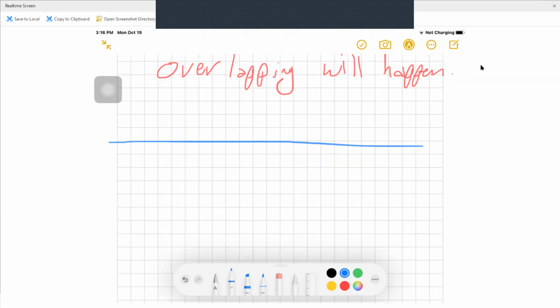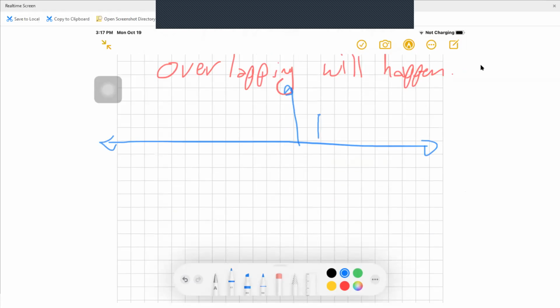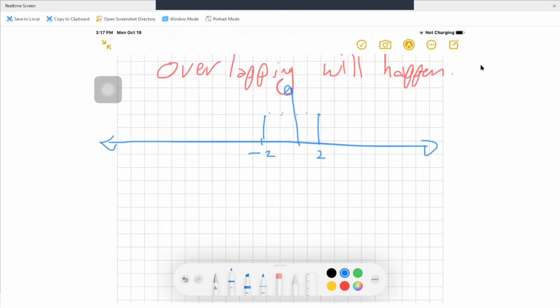Okay, starting with the spectrum of the signal. Of course, going back to the same story. Well, here we have two frequency components, 2000. Of course, the 2000 frequency magnitude will be 2.5, for 2 kilo and minus 2 kilo. You know, by now you are familiar with the Euler identity, so you can use it easily.